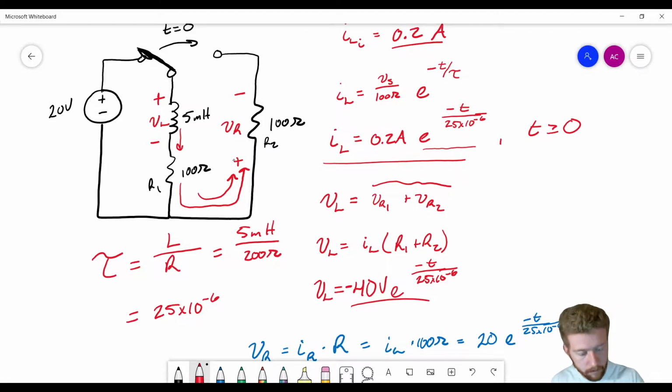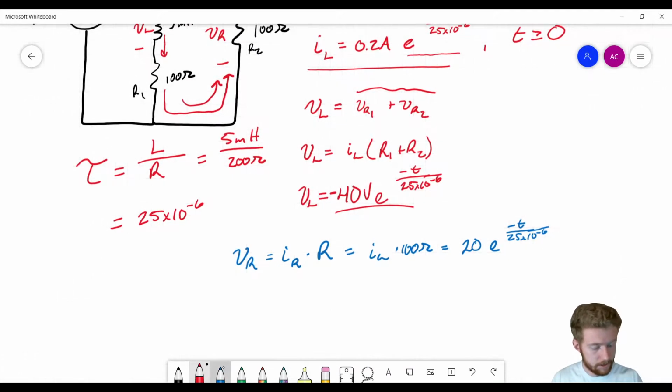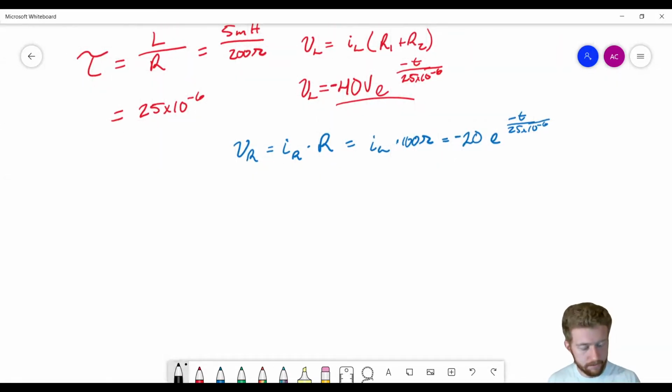But because we wrote it backwards, because it's negative and positive, we're actually expecting a voltage rise in this case, because if we go from here down to the bottom, that voltage is actually going to increase. Okay, so this is actually, once again, a negative value. And all that has to do with is the way that the plus and minus were written. Okay, so that's something important to keep in mind, that the polarity of voltage does matter. Okay, so if you have the backwards signs, then that's going to cause you to get a backwards answer or a negative answer. So let's graph these two.